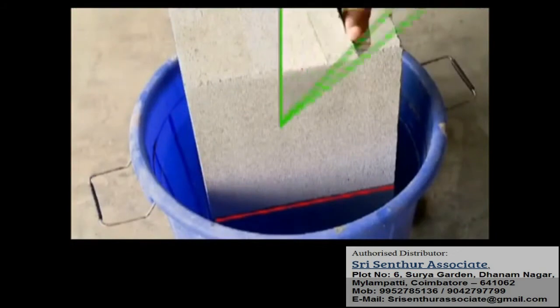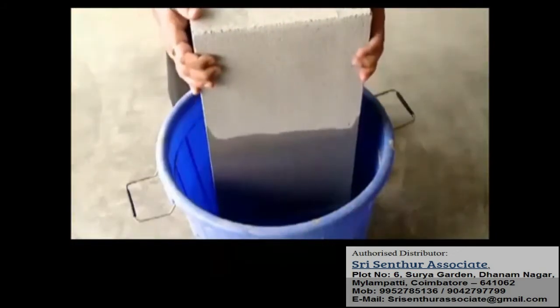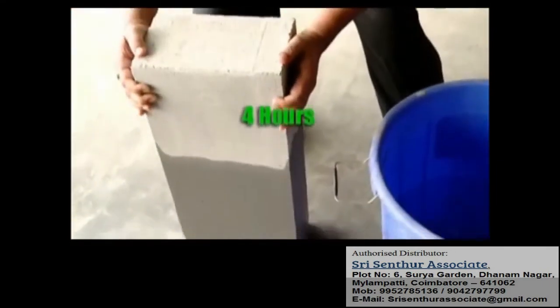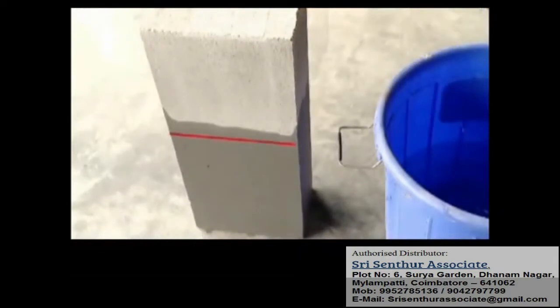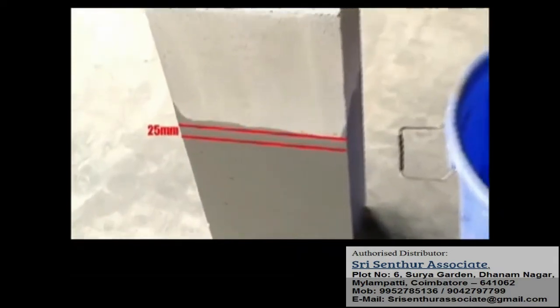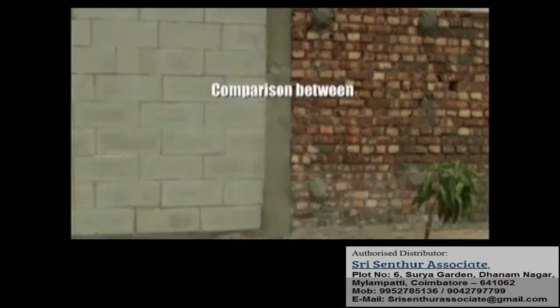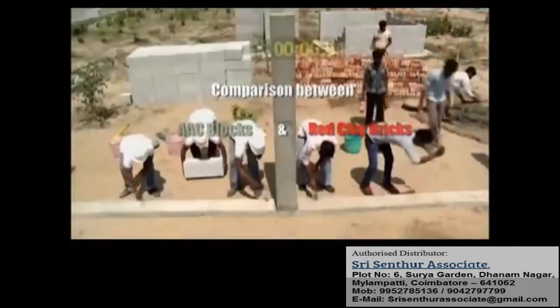In another experiment, when a half-immersed block is taken out of water after 4 hours, we notice that the level of the soaked water by osmosis had increased by 25 mm only. Let us now compare the advantages of building walls with AAC blocks in comparison to red clay bricks.